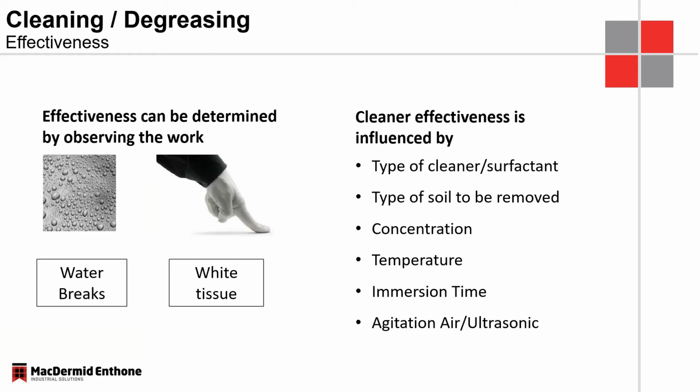Immersion time, again, this is very much dependent and dictated by our anodizing line and how much time we have available in the cleaners. The longer, the better, without having any attack on the surface. One very, very effective way of increasing the effectiveness of our cleaners is introducing air agitation.